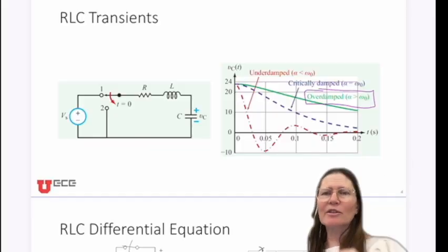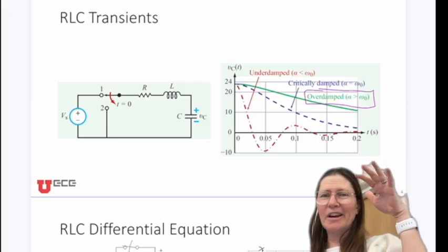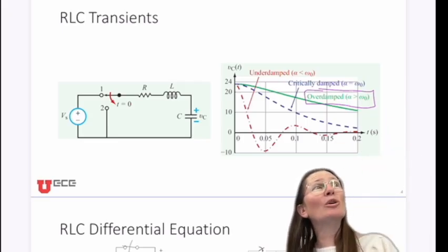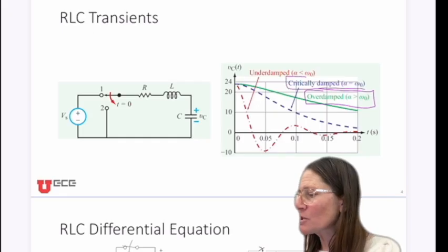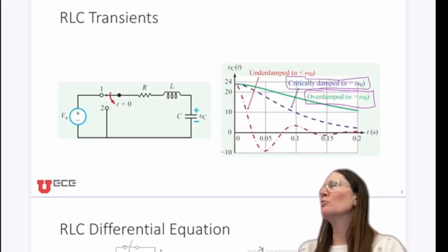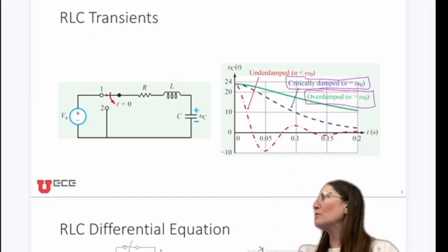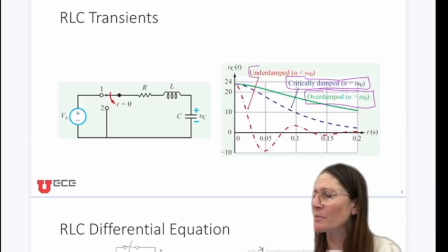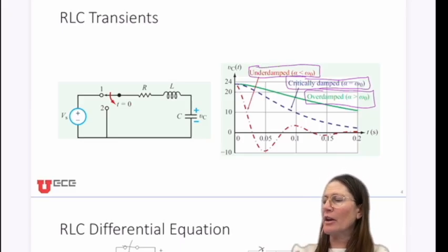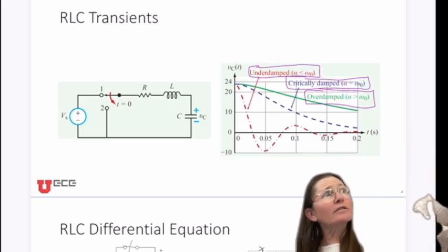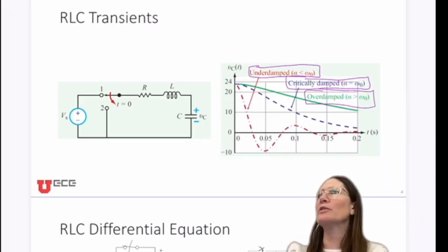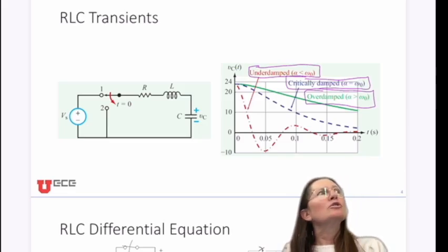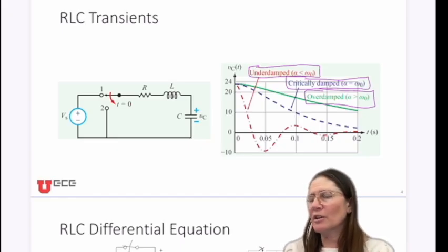You can see it kind of as a, whatever you want to call that, so it doesn't look as much like the exponential. The critically damped one looks more like that exponential form, so that is the one where you're more used to a discharge type of look. Underdamped has complex roots, and so you're going to see it oscillate like that due to the complex roots that it has. So 3 different types of responses based on the roots of the system.